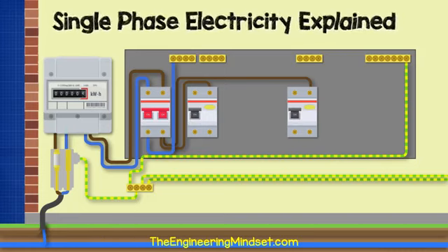The RCD will trip when it believes the current is unsafe, even for a fraction of a second. It does need to be manually reset to restore the power, but this does not solve the problem and you should locate and remove any faulty appliance or fixture.